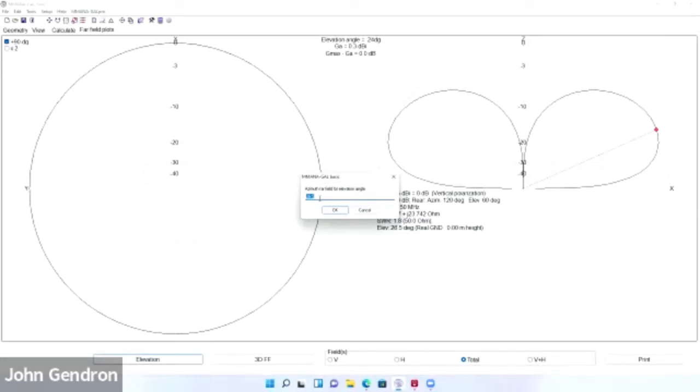So when you start talking about refracting a radio wave, every time that radio wave refracts, you lose energy. It attenuates. So if we're going for DX, we want a low radiating angle, so we get a longer distance to travel before it refracts. And then it'll refract off the atmosphere at that same angle and return down.